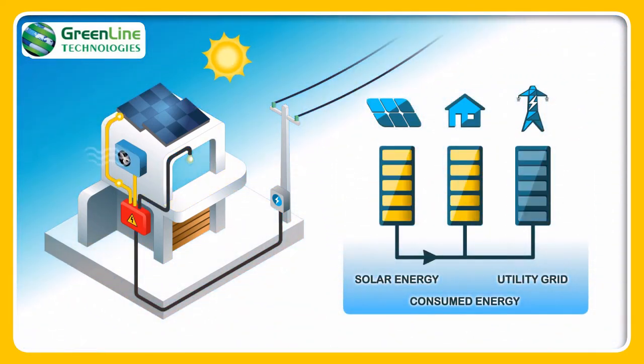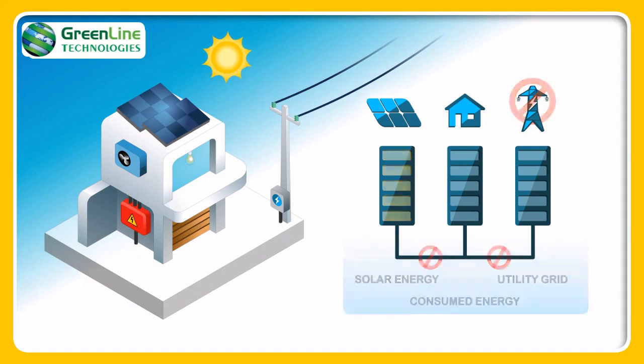You can always rely on the grid to supply extra electricity when needed, except during a power failure. When the utility grid fails, grid tie systems will not operate, not even on solar power. This allows utility employees to fix the power lines safely without worrying about solar energy systems that are still feeding electricity into the power lines. In areas with frequent power cuts, an additional battery backup system is advisable to supply energy in case of grid failure.